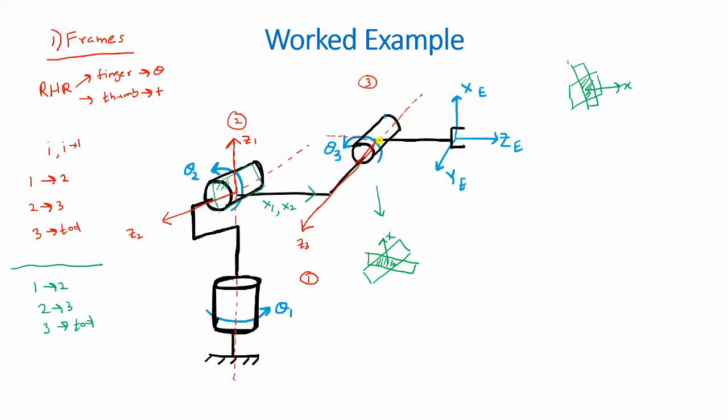So therefore, from this point, x-axis would point upwards, x3. So again, you can see that x1 and x2 are sort of opposite to the direction of rotation theta 2, while x3 is opposite to the direction of rotation theta 3. That is why we know it points upwards.